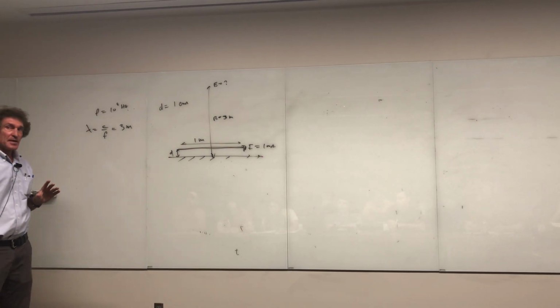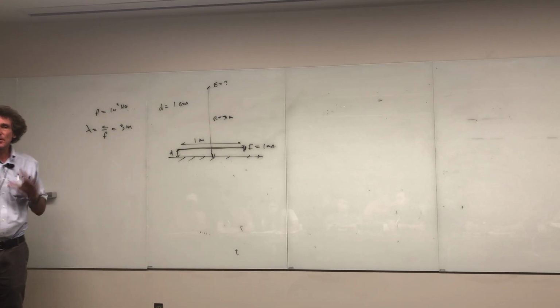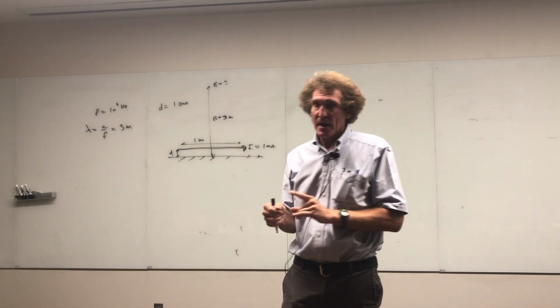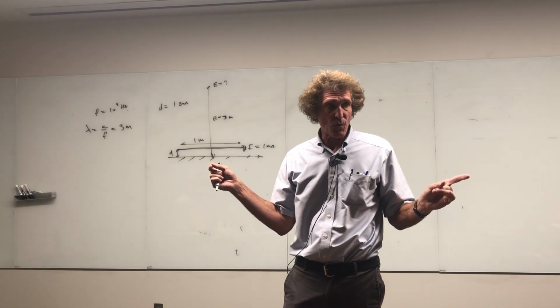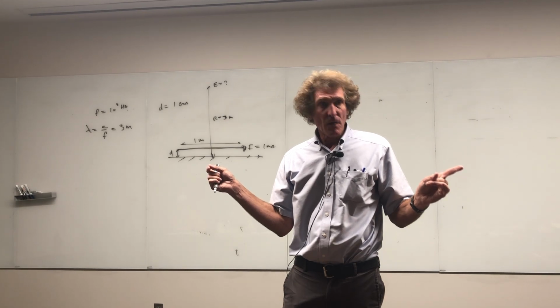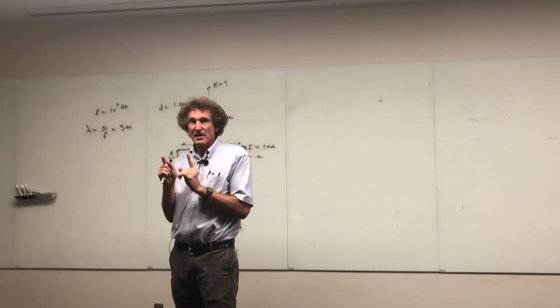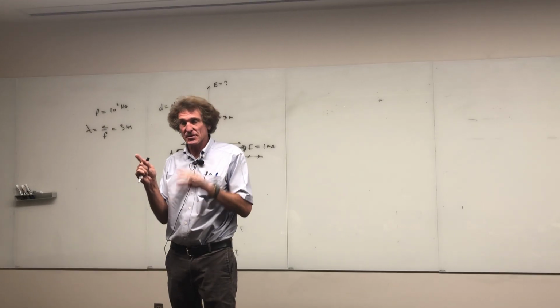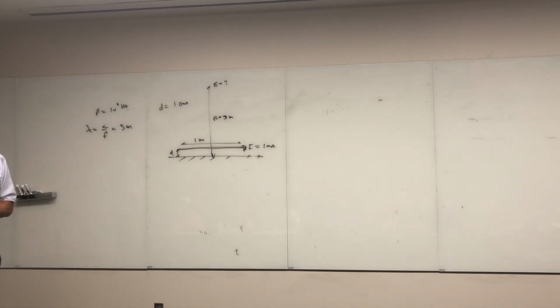For this purpose, usually, even though this isn't exact, it's still pretty good. If you think about what's the difference in gain between a short dipole and a half-wave dipole. What's the gain of a half-wave dipole? 1.64. What's the gain of a short dipole? 1.5. Not a lot of difference. If you're right in that region, about a third of a wavelength, you're going to get about 1.5. It might be just slightly less, but it's close to it. Do you follow me, class? So if you default to a short dipole, you're going to do fine in this one in terms of the approximations for what this wire actually resolves to.